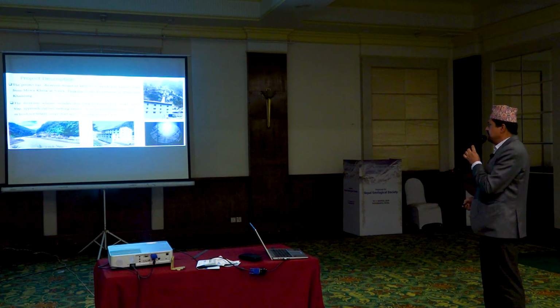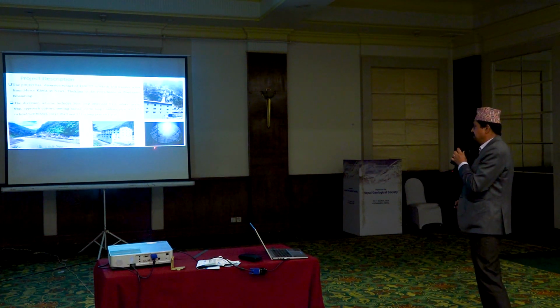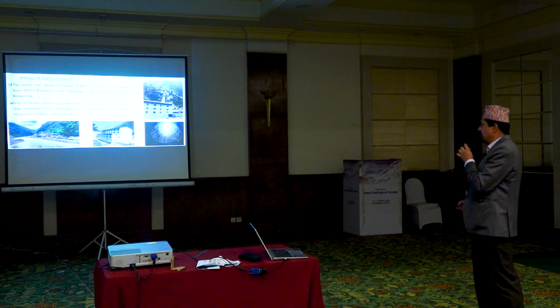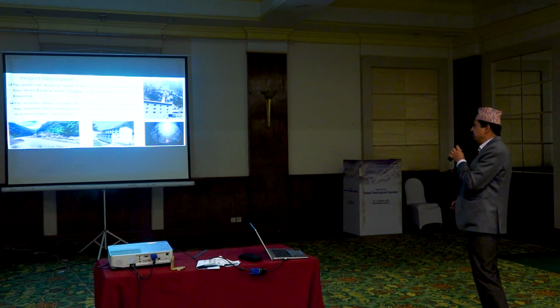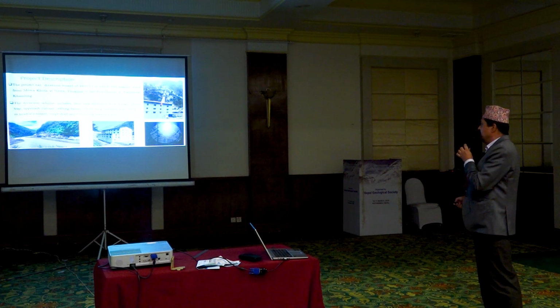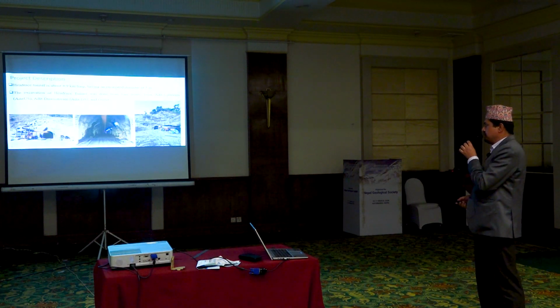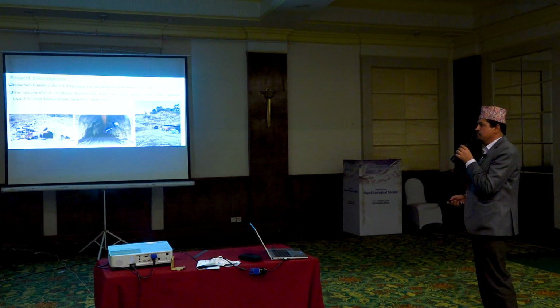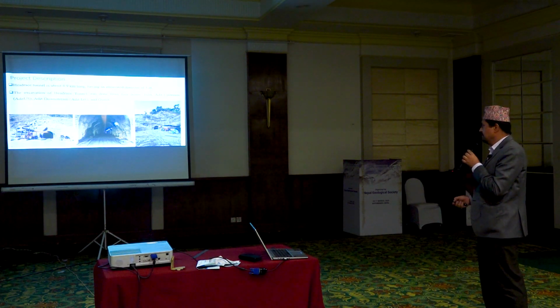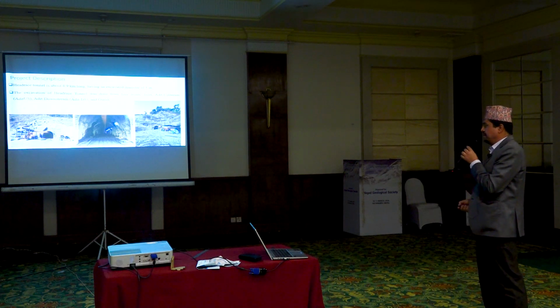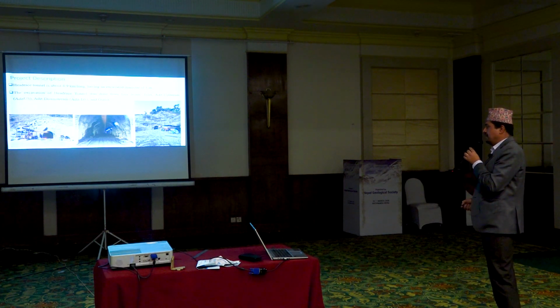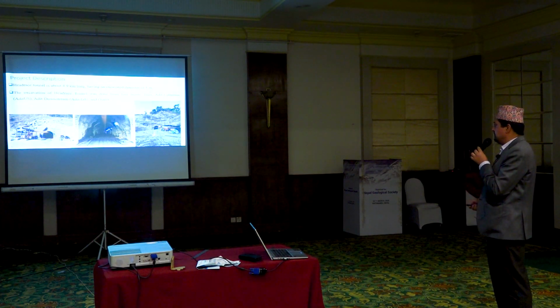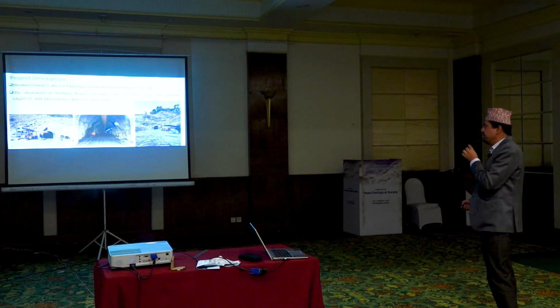This is the headworks of the project site. This is the powerhouse site, and we can see this is the surge shaft which is 8 meter diameter after completion of concrete, and the excavation size is 9.2 meter. This is the penstock line, and somewhere here is the outlet portal. For the construction of this project, there were 3 portals: 1 adit and 2 inlet and outlet portals. This is the adit portal from where the excavation was carried out, and upstream and downstream portions were excavated. Similarly, this is the outlet section and this is the inlet section.